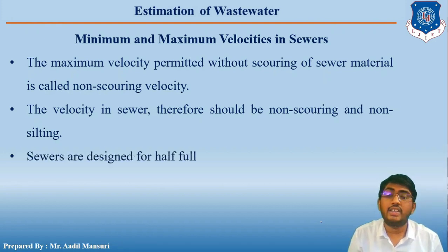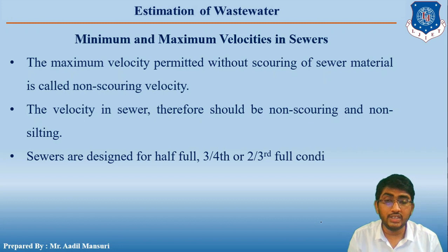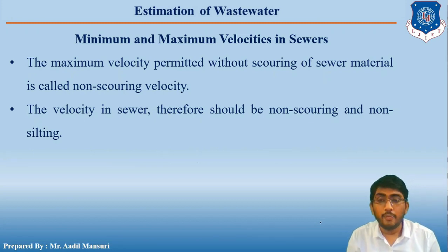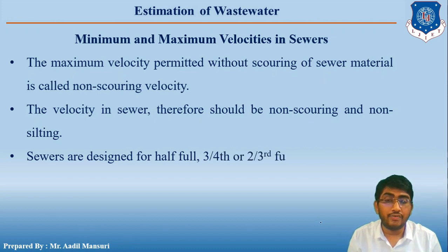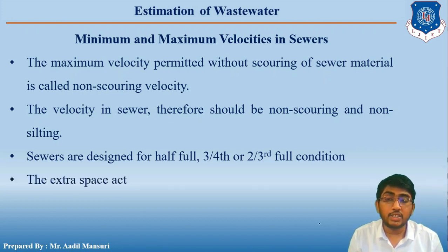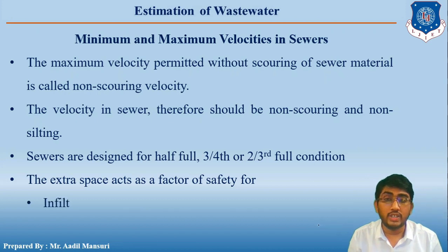Now sewers are designed for half full, 3/4 full or 2/3 full condition, because the extra space acts as a factor of safety for two reasons. First is infiltration, that is, external water coming inside the sewer.